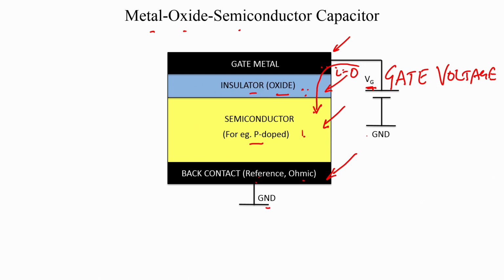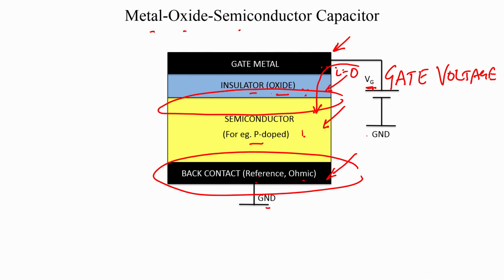As usual, let us start by looking at the band bending diagram. We will take the gate metal. We will assume the back contact is an ideal ohmic contact and not worry much about it, because everything interesting with regard to this device happens at the insulator semiconductor interface. This is the region of interest, because that is where the junction is.